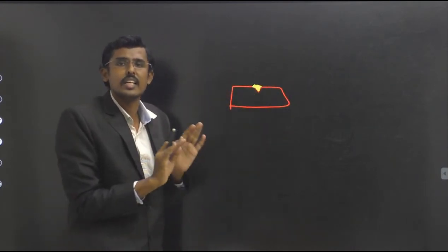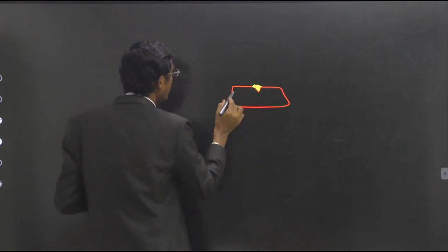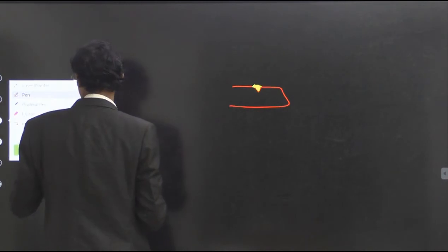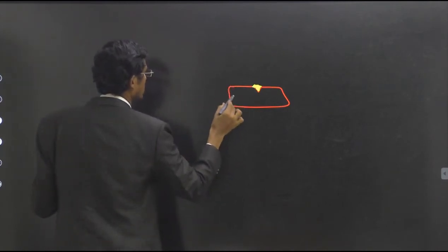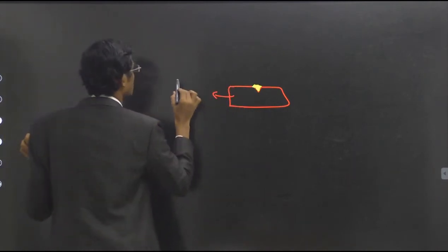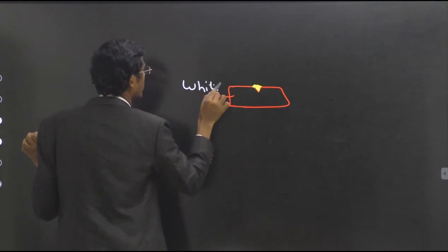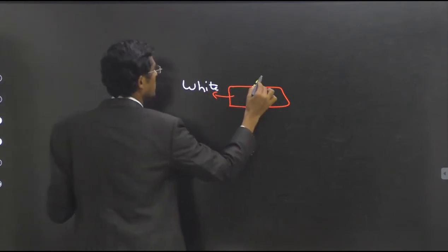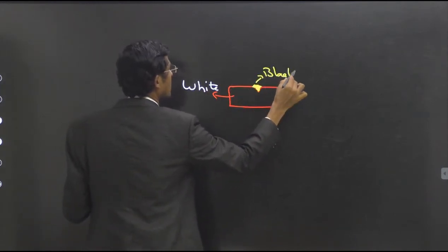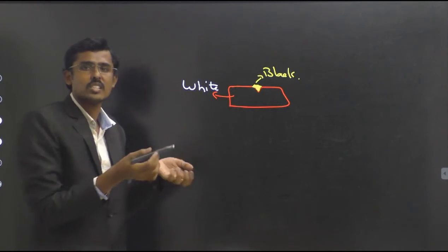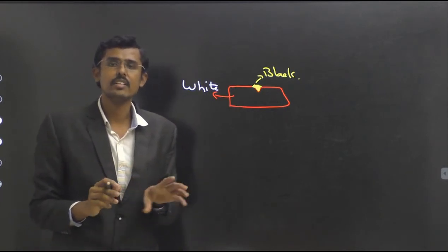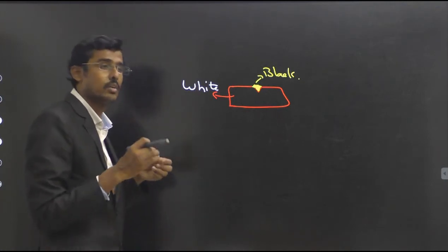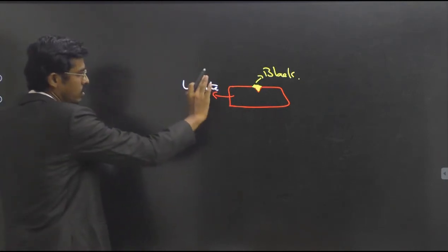Therefore, it stays there. The surface is white and the crack is black. So out of contrast colors, we are able to identify this. This is what they did. But now recently we are using penetrant color liquids. Earlier they used carbon black.